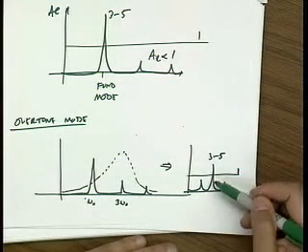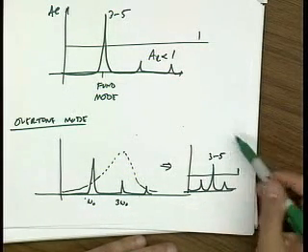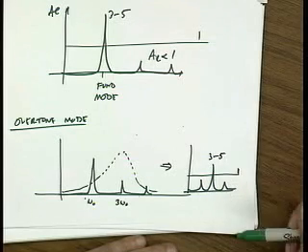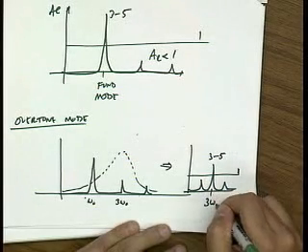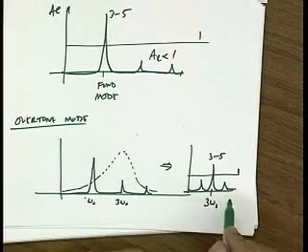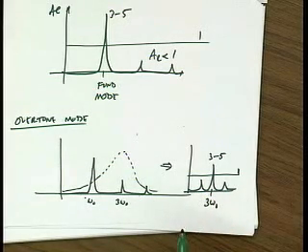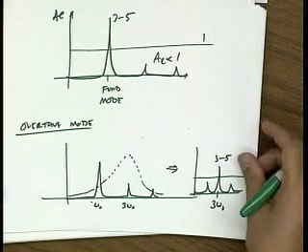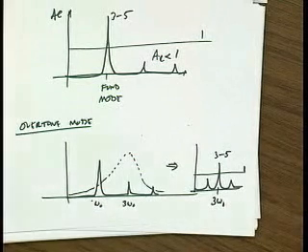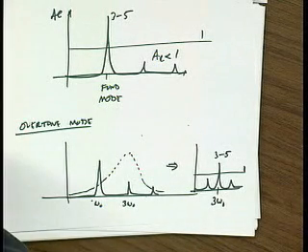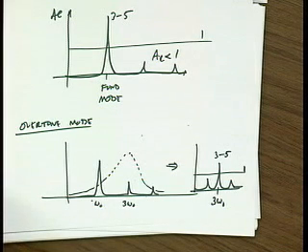So now the loop gain is bigger than 1 only at one frequency. That's at the frequency that I desire, which is 3 omega naught, and I've suppressed the fundamental mode. Okay? Questions? Good. All right,